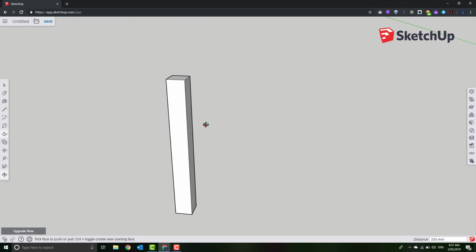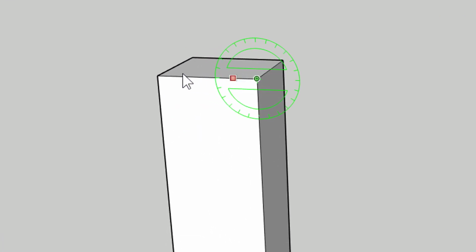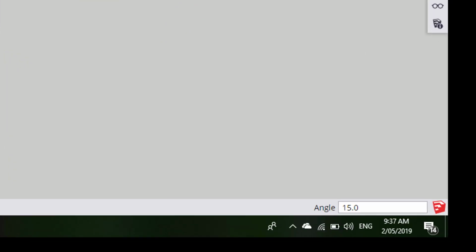Now, the leg's going to be angled at 15 degrees, so I want to draw on 15 degrees. In the woodwork room, we'll use a sliding bevel, because we won't have anything that's 15 degrees. In math, I would use a protractor. So I'm going to get my protractor. I'm going to come up and mark the corner here, bring it along that line, because that's the line I want to adjust. Along that line, and now I tell it 15 degrees. So once again, I just type in 15. I've got 15 degrees there.